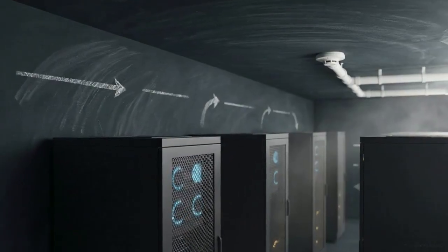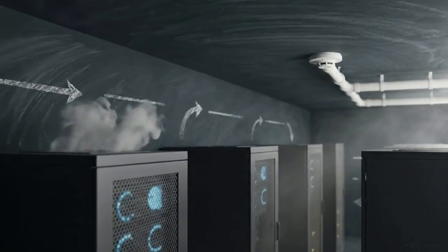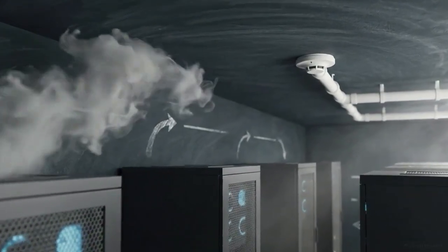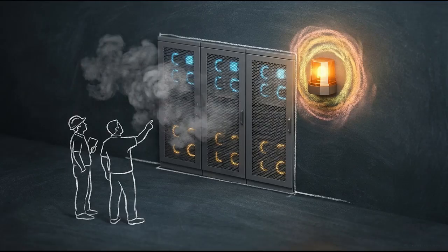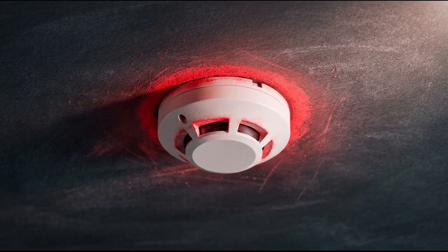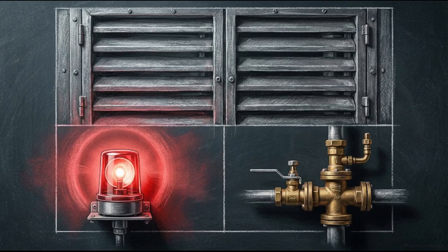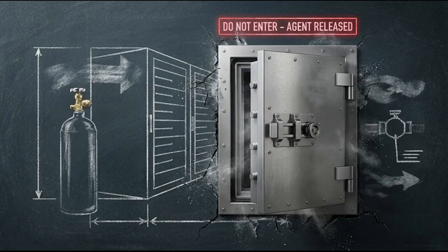System resilience is proven through operational edge cases. Consider a scenario where aspirating smoke detectors identify incipient smoke inside a heavily occupied control room. The first alert triggers local warnings, allowing trained staff to investigate the source without immediately initiating a dump. If the fire escalates and triggers a secondary detector, the panel confirms the fire, isolates the HVAC dampers to prevent gas escape, sounds the evacuation strobes, and commands the release sequence. The logic prevents a premature discharge while securing the room for agent retention.